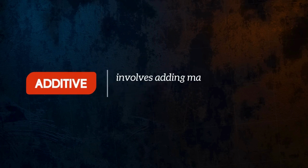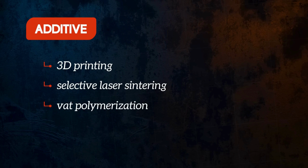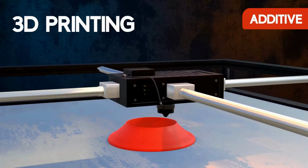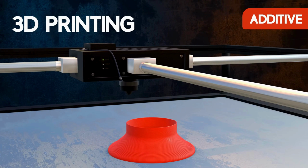The final category is additive manufacturing, which involves adding material to build up the desired object, typically one layer at a time. 3D printing, selective laser sintering, and vat polymerization are examples of additive manufacturing techniques. For 3D printing, a computer is used to successively build up an object layer by layer. 3D printing is a slow process, and the range of materials which can be used is limited. As a result, it tends to be used for prototyping rather than for mass production. That's it for